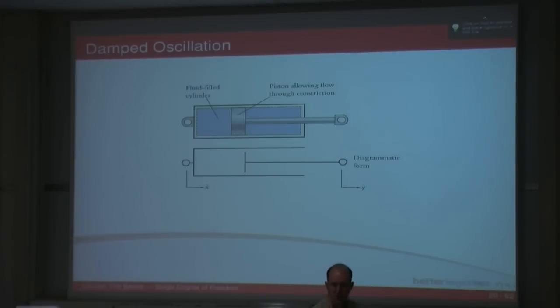So, that helps us with damping. It's going to be a classic example of where using the complex plane is a lot easier than trying to do it any other way. Damping. What do we know about damping? Well, there are two types of damping. There's a type called viscous damping, which is a force on a system that varies as a function of the velocity. So if something's not moving, there's no damping. But if it is moving, the amount of damping force will depend on how fast the thing is moving. That's called viscous damping.